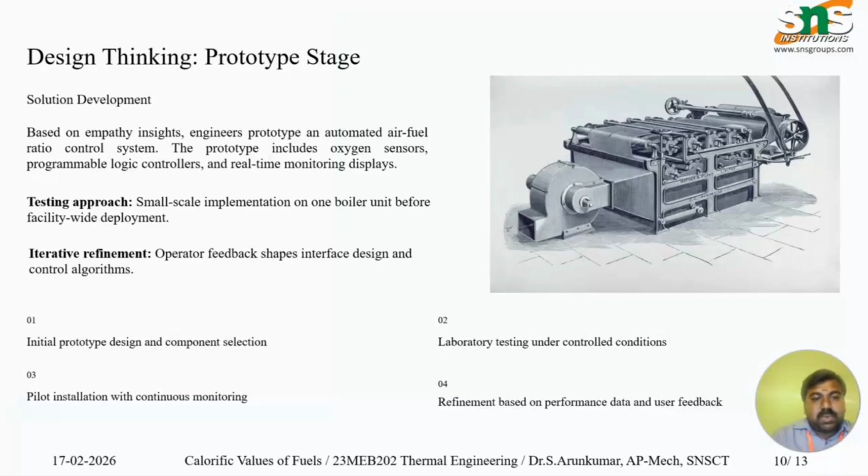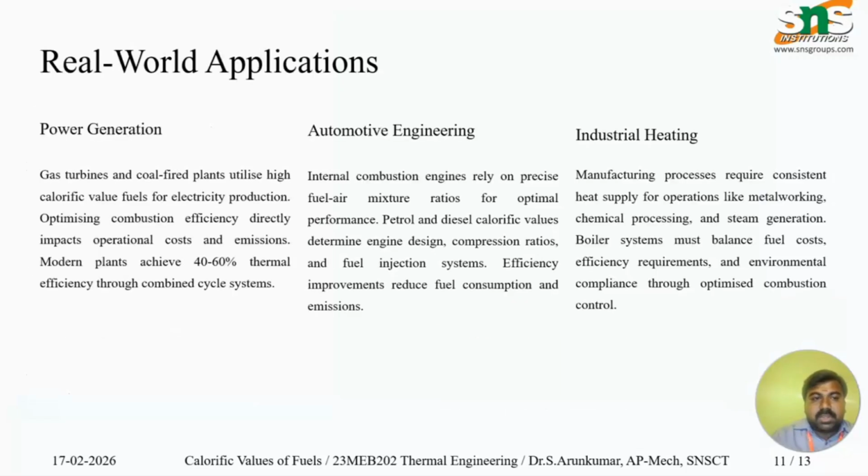Testing approach: small-scale implementation on one boiler unit before facility-wide deployment, and iterative refinement. Operator feedback shapes the interface design and the control algorithms, with initial prototype design and component selection, laboratory testing under controlled conditions, pilot installation with continuous monitoring, and refinement based on performance data and user feedback.